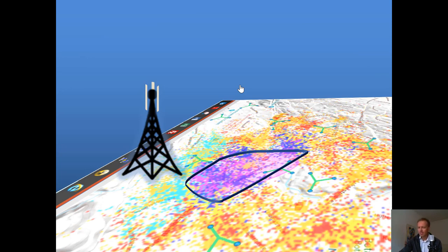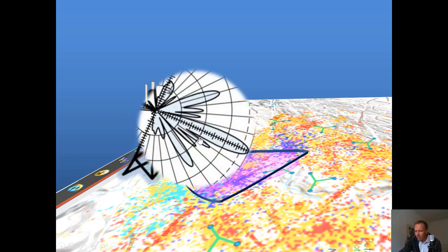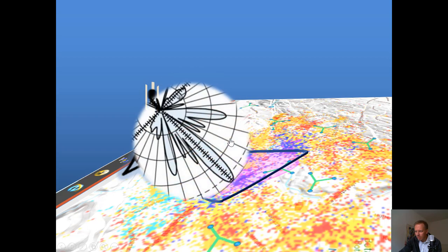Now let's take a look at it more closely. How would this tilt impact the radio network? Let's imagine that we actually did the tilt. So here's the old value for the tilt, and here is the new value for the tilt. If we compare those two cases, we can see that we were able to potentially decrease interference by 20 dB on the main lobe area where we had lots of interference.